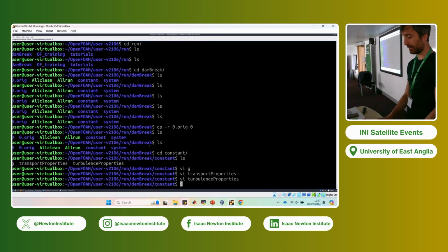Even though I guess you're aware that typical turbulence models are developed for single phase flow. So if you want to do a two-phase flow simulation with the typical Reynolds averaged turbulence models, I'm not really sure if you can get meaningful values of turbulence at the interface.